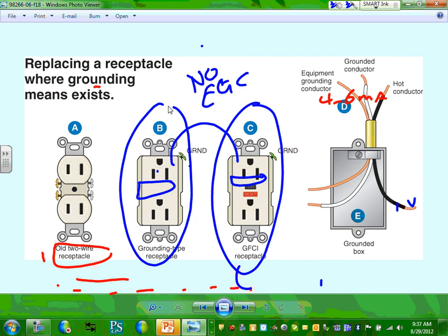One more time. You're changing a receptacle like this. Option number 1, buy another non-grounding receptacle like it, stick it there. Option number 2, put a GFCI receptacle right here. Make sure you put a label; it comes with it: no equipment grounding conductor. Option number 3, have one like this and put it in here, but it has to be fed from a GFCI, which just makes it hard. So these are the options you have, typically most of the time. What I've done there is just put a GFCI receptacle with a no equipment grounding conductor label.